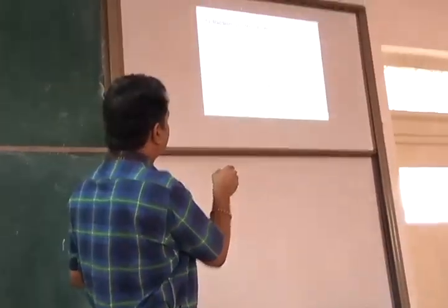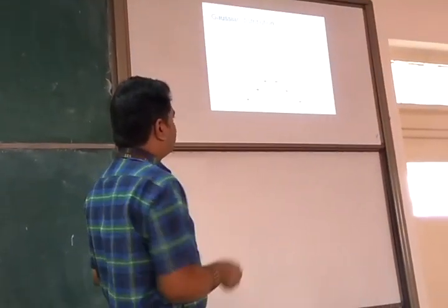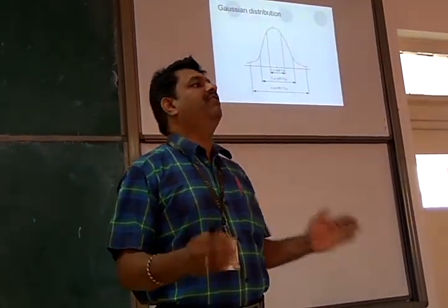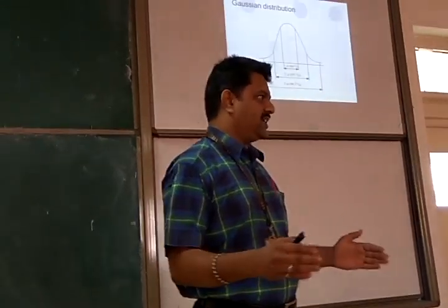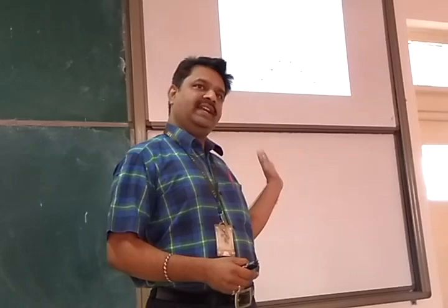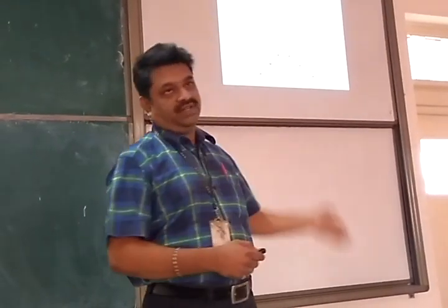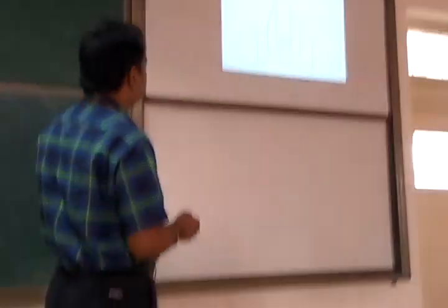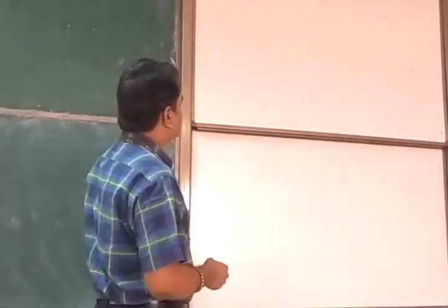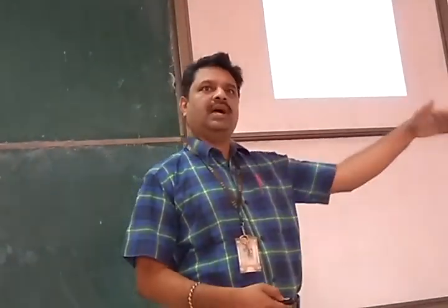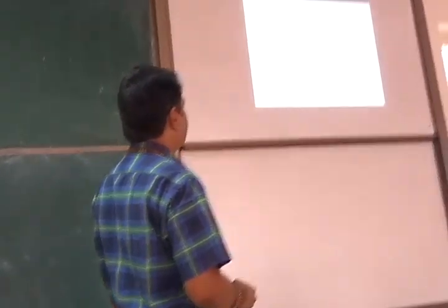Mostly, if it follows a Gaussian distribution, 99.7% of the measurements that you have made will fall within the 3 sigma range. If you produce 100 components at 3 sigma level, 99.7% of items will fall within that. So this is normally how you quantify your errors with the help of your standard deviation, histogram, and Gaussian distribution. You generally understand.